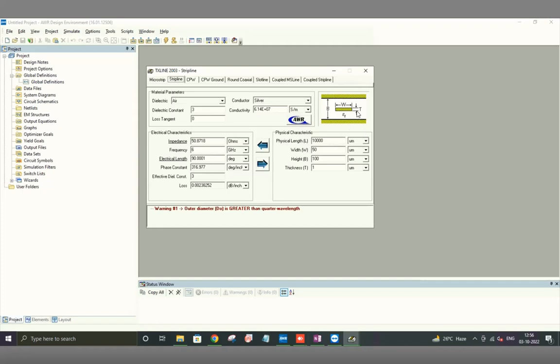So again, what are the relevant numbers here? The width, the gap, for similar reasons to that of the coax. If I reduce the width, it's like a thinner center conductor. So inductance is going to go up. But at the same time, it also is one of the plates of the two parallel plate capacitors which are now happening between these two and these two plates.